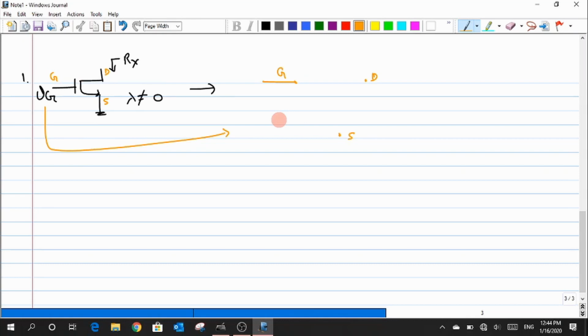Can I carry the entire composite signal to the small signal model? Only the AC signal component I need to carry in, right? So I have the small VGS or Vg, and I can also define some polarity here because the polarity is important for us to draw the small current ID. Now I've used this positive polarity of my signal, and I also mark the other nodes where it is connected.